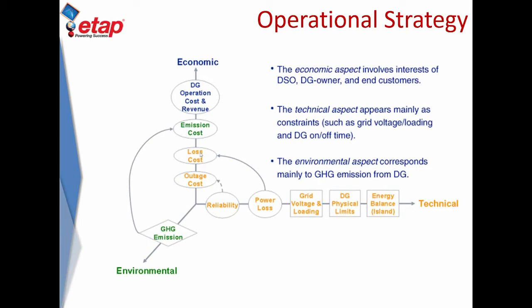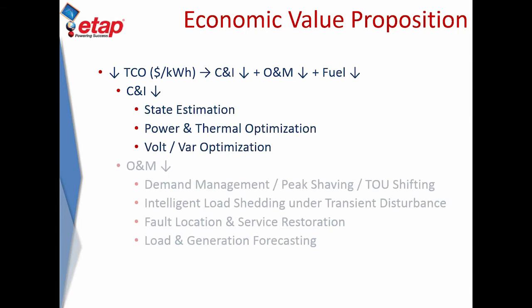And when we optimize generation, we essentially have to look at power losses, how to minimize those, improve the system reliability, because those are low-hanging fruit, minimize the cost associated with them, as well as the maintenance cost, and then finally, to a certain extent, the greenhouse gas emissions as well, if there are certain constraints associated with it. So when we talk about generation optimization, we're talking about optimizing from all aspects, and it makes it a multi-objective optimization problem.